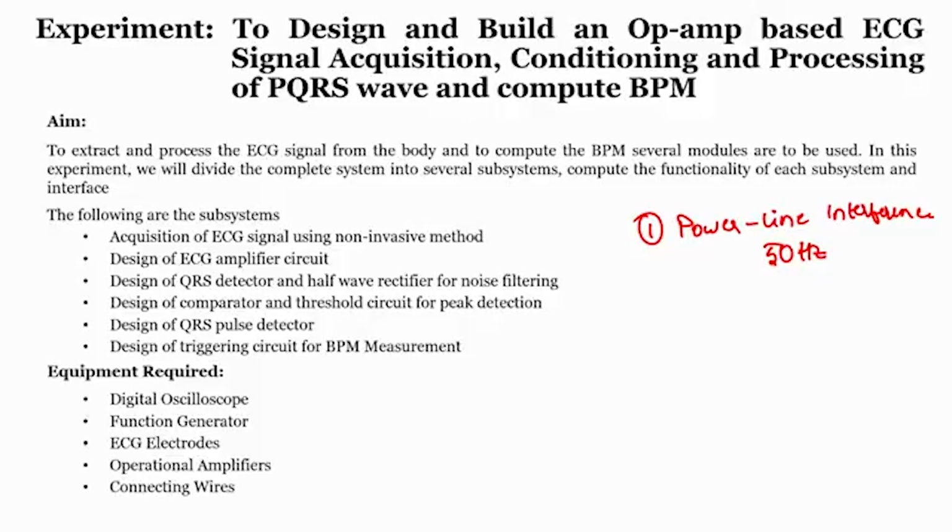So, for frequencies like 50, 150 and 300 hertz and beyond, we may not require all these frequencies. To remove them, we should know the frequency range of our ECG signal. Generally speaking, the ECG signal frequency is around 0.05 hertz to 120 hertz, or generally they also say up to 100 hertz.